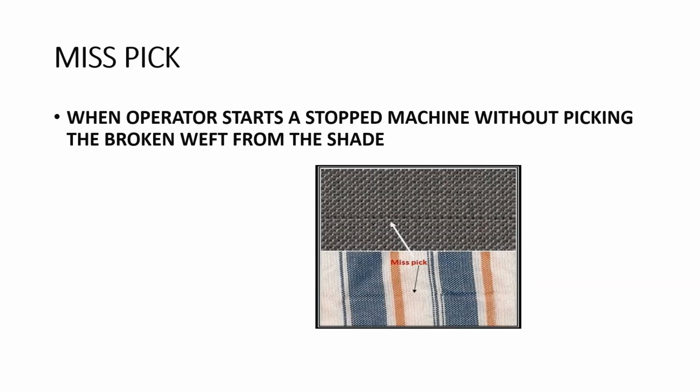That is the way the woven fabric defect is classified, and it is normally visible to the human eye, and if you do the impact assessment, yes, this has a good impact on the quality. So that is called the mispick and can be treated as a major defect.